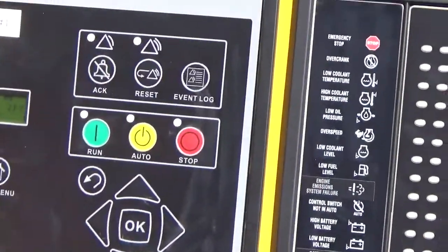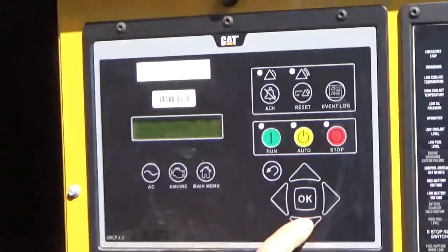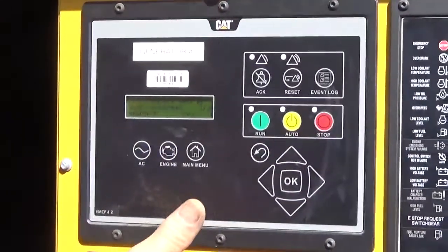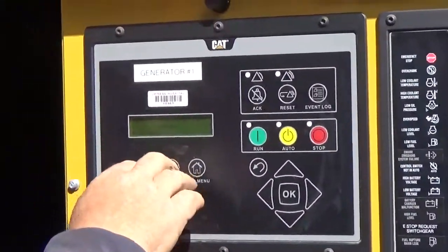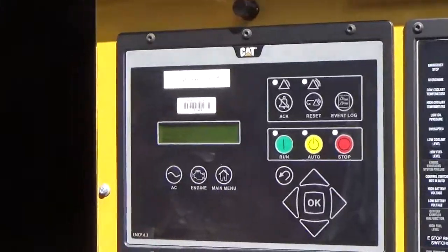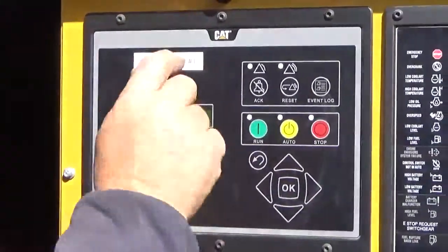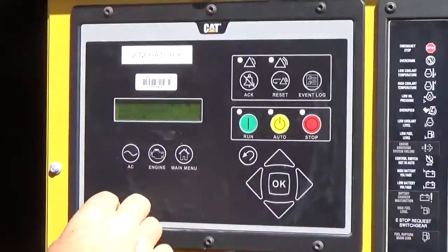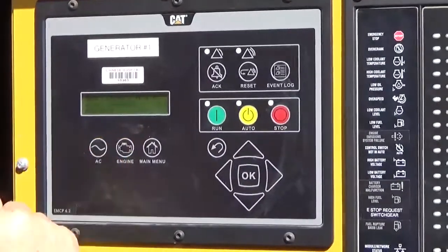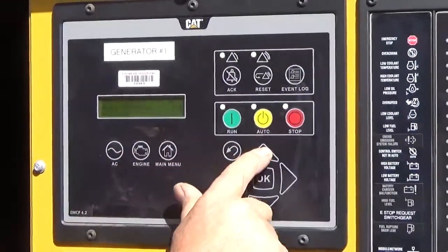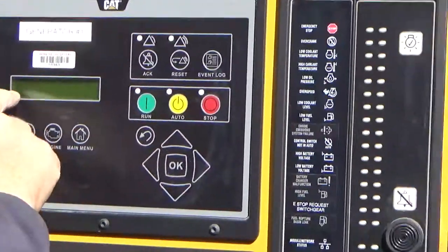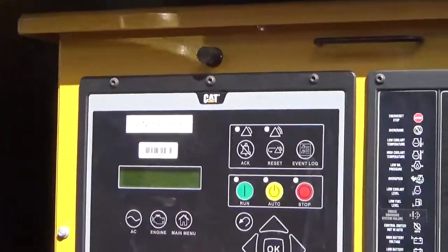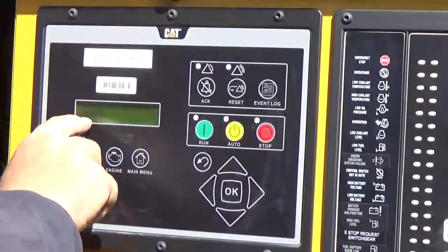So if there were more alarms stored in there, when you go down, it'll go from the last one under this that happened, in successive order, in the order that they happened. So you can read, there's another one present because you've got 2 of 2 there, right? So if you go up, when you hit 1 of 2, there you go. Yeah, and that's present because they have this wired in, and your breaker is closed.